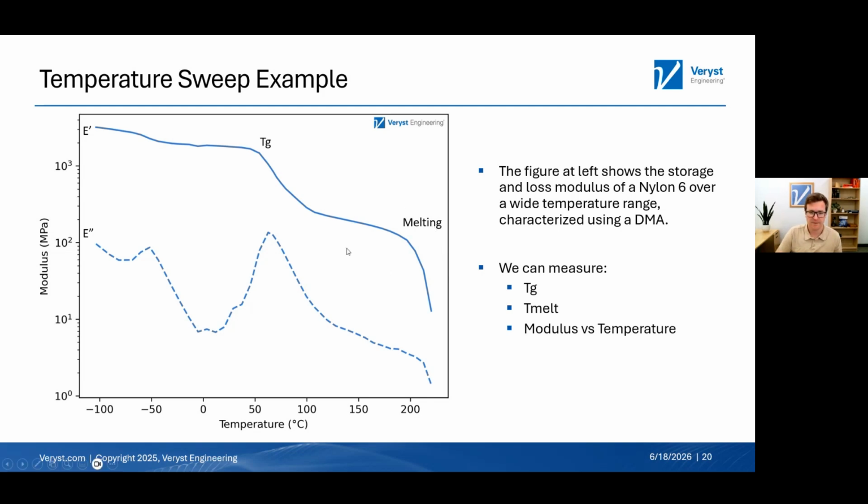But whether or not you're picking out these numbers specifically, the real value from this temperature sweep is just the modulus as a function of temperature. It tells you that at a temperature of 50 degrees, we expect our modulus to be a little bit less than 2 gigapascals, and at minus 50 degrees it's going to increase a little bit, to not quite 3 GPa. Whether that difference is relevant for your application is part of your analysis.